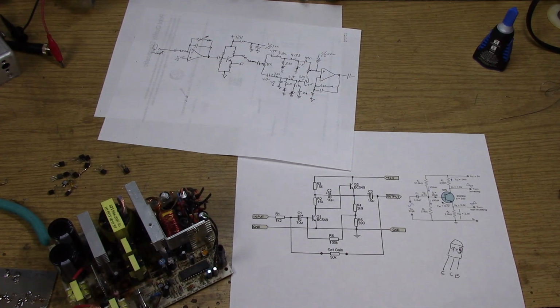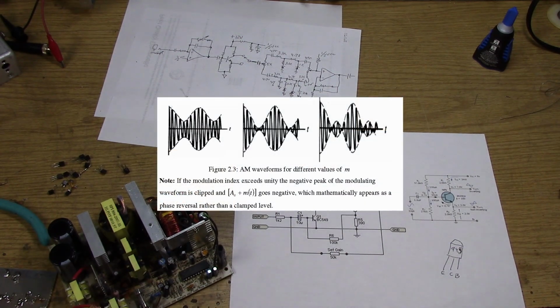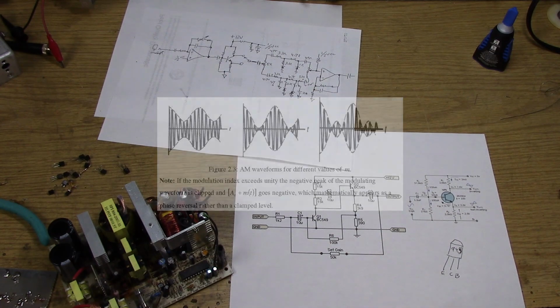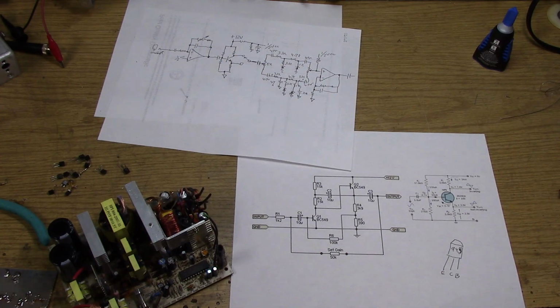There's no doubt we need an audio amplification system for our microphone that's going to allow us to both adjust the tone or the equalization of the audio, as well as to perform some negative peak clipping so that we can modulate upward and not overmodulate below zero, causing distortion. On top of that, we would like to have a fairly low noise amplifier and bring the gain up a little bit because we were a little shy on gain.